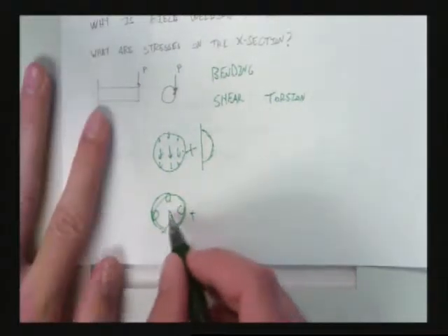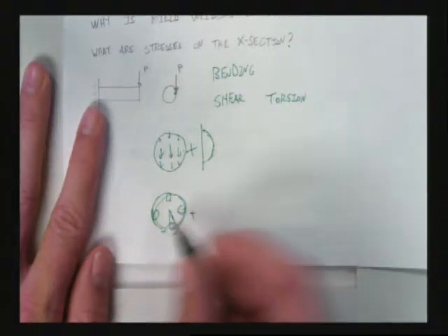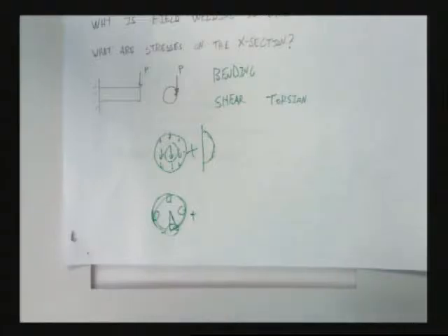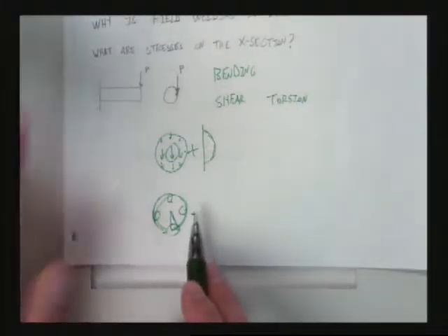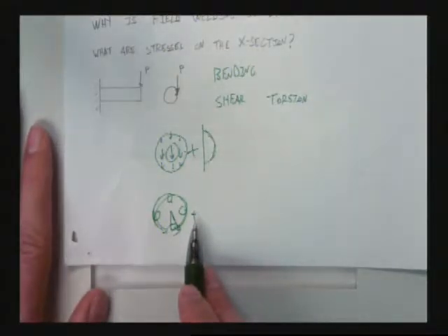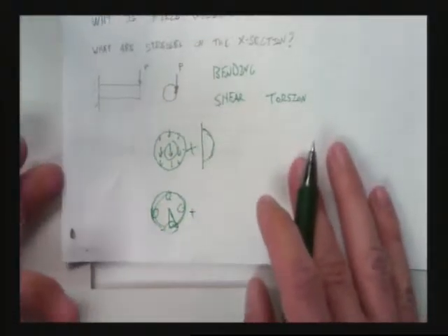How about at the center? Well, there's no torsional stress at the center, right? But yet there's the highest amount of shear stress. These are all concepts you should be able to do quickly. Now, why are we covering all this? Well, it's because this is analogous to some of the problems we've seen before, and it's analogous to the exact same thing we're going to be doing in bolts. And welds, we'll find out. Exact same thing. Any questions before we move on?